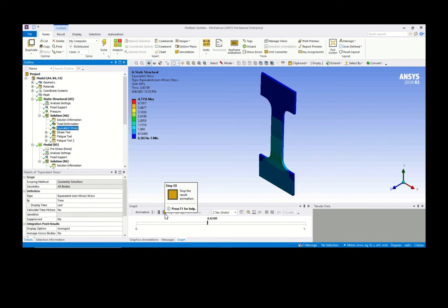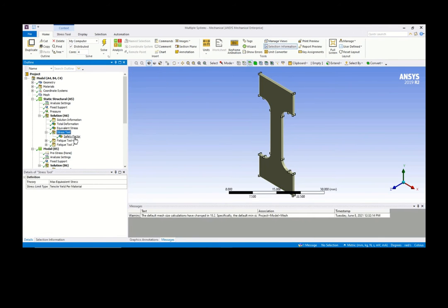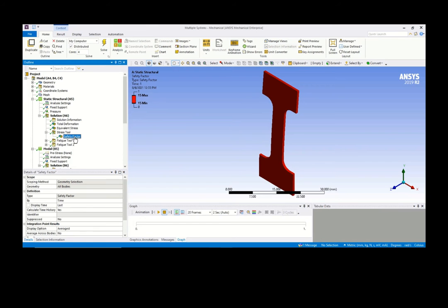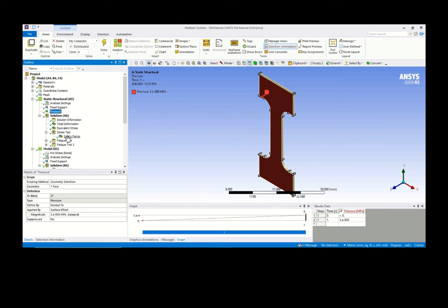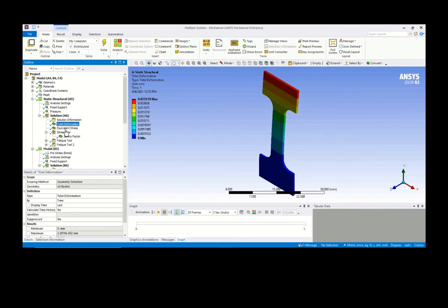If you remember, under failure analysis, we called out the stress to find the static failure factor of safety. We found that it's above 15, all are 15 and above, so basically all very safe, no issue at all. So no static failure will happen if you apply 500 Pascal on this particular surface. These deformations inducing this stress will not cause any static failures.